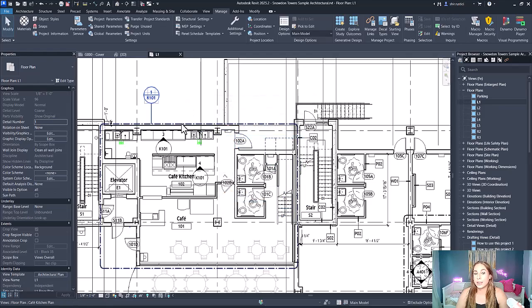Shared parameters, on the other hand, are the heavy hitters. Shared parameters are custom parameters that you can use across multiple projects. They live outside your Revit model in a shared parameter text file, which allows you to use them in different projects and maintain consistency across your firm. These shared parameters also allow you to communicate with other files in the project, such as families or annotations.